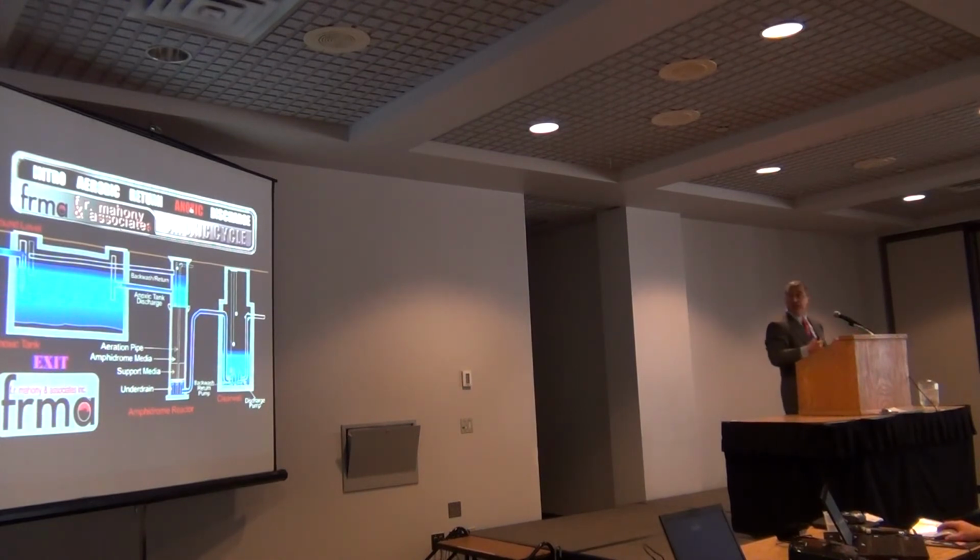Then what we do is we bring it back through the filter, but with no air. And so now we've got the requisite carbon, because that came in recently. It hasn't gone through under aerobic conditions and been treated. We can now go through the reactor without air and tend to force the reactions toward the denitrification, the third reaction, which requires the organic carbon source. And so this cycles back and forth, and at the end, we discharge typically 6 times per day, and most of the systems we've designed to date have been to some sort of a soil absorption field. There have been several surface water discharges, but that's kind of up to what the permit is.